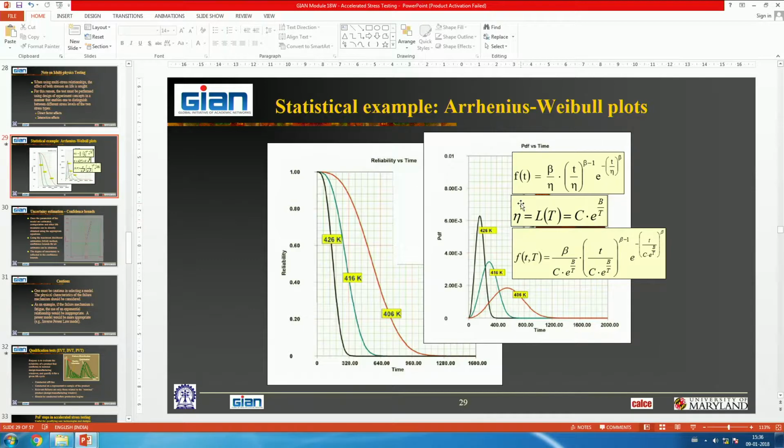So what we do is we look at the Weibull distribution. This is the Weibull probability density function. It's a 2-parameter Weibull in this simple case. That means gamma is 0, so you see there's no gamma. There's just eta and beta. And so what we do is we take the Weibull eta, which is the Weibull characteristic life, and we use the physics of failure model to describe eta. As an example, if the failure is getting accelerated by temperature, it responds to just temperature, then you take one of your temperature models. This could be Arrhenius dependence on temperature, and you say that your characteristic life is dependent on temperature. The beta does not change with temperature. So wherever there's an eta, if I substitute back this temperature dependent function, then that gives me a stochastic physics of failure model. Now I get a full distribution.